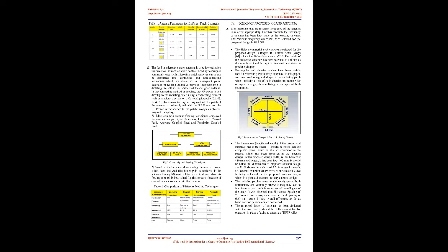The 32x16 array operation of the BFSR, SR results in a gain of 31.82 dBi, a realized gain of 29.90 dBi at 10.2 GHz, and a directivity of 33.89 dBi. The radiation pattern obtained at 10.2 GHz, in 3D and polar representation, is shown in the figures below.